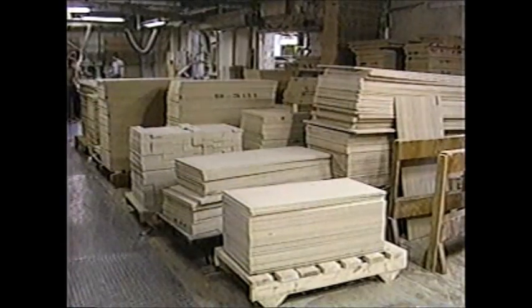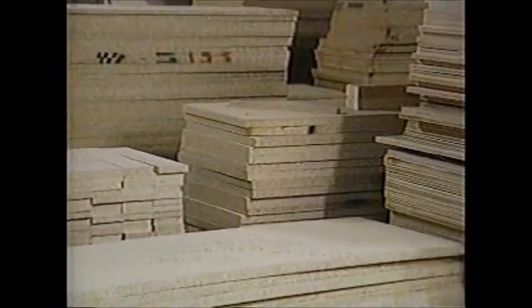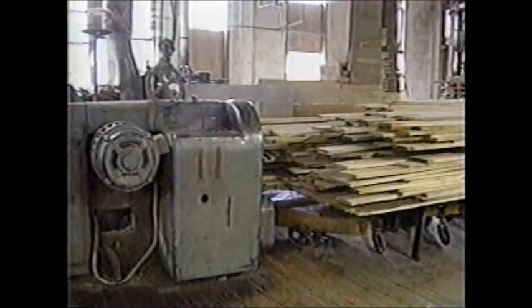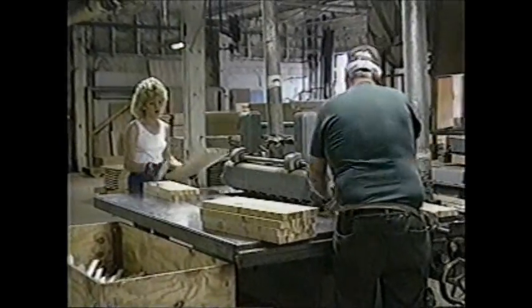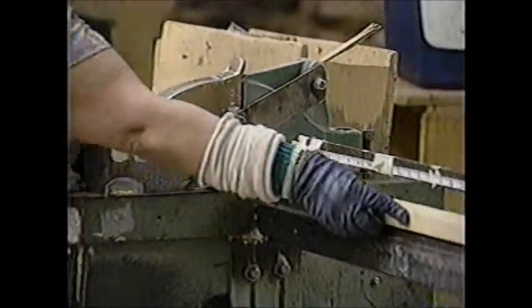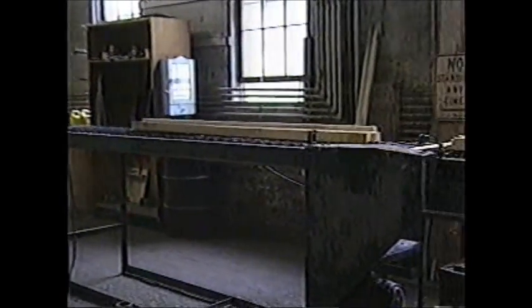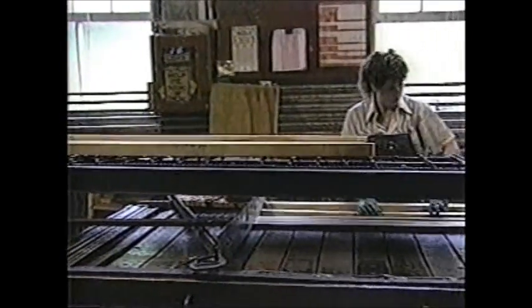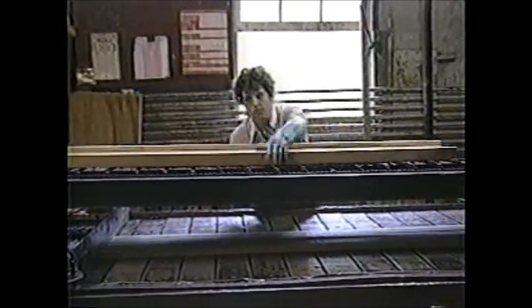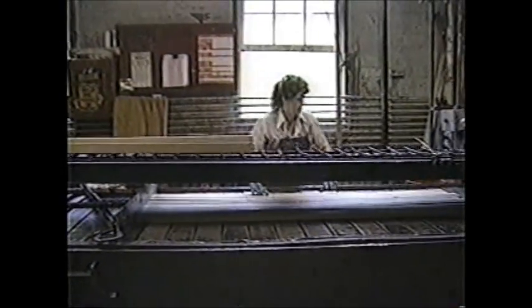Hardwood plywood can be manufactured with a lumber core, a particle board core, or a veneer core. In lumber core plywood, the material for the lumber core is first planed, ripped to width in a straight line rip saw, and then cross-cut to length, removing defects. The cut-up stock is run across a glue roll, which applies a layer of glue to one edge. The pieces are then laid up and run through a radio frequency hot press where the strips are joined under heat and pressure.